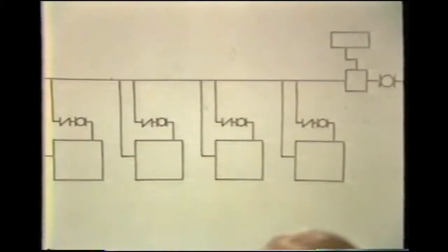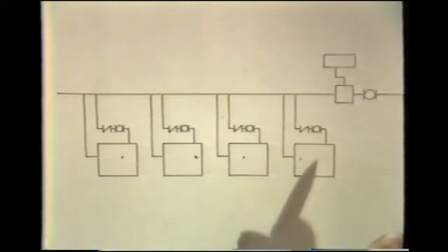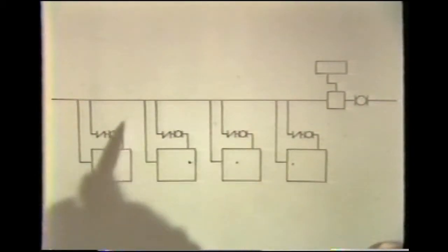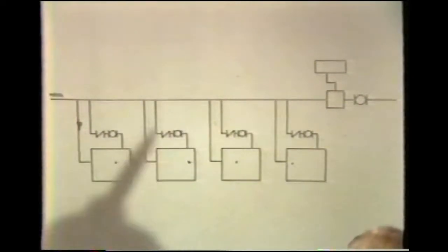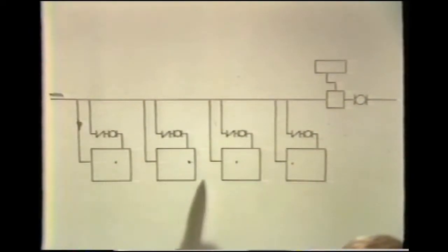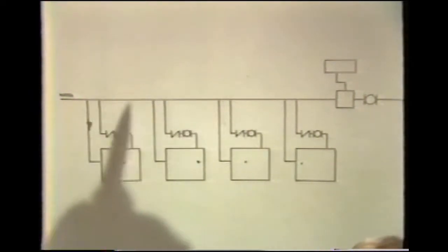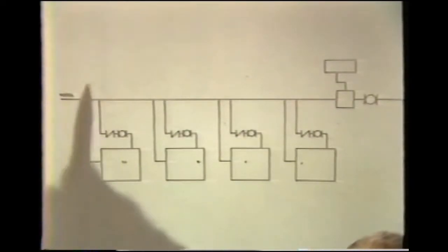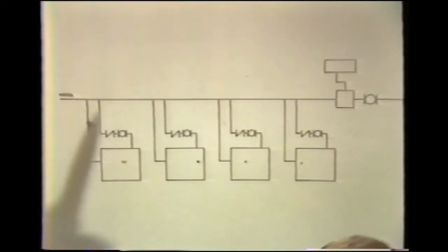into a discussion of the usage of primary, secondary pumping with boilers in equipment rooms, we can utilize boilers placed in series, each with their own pump, and operating in such a way that taking their control from the return water temperature, the pumps will cycle, starting and stopping to deliver hot water so as to maintain a basic return water temperature from the system, which can be stated on reset.